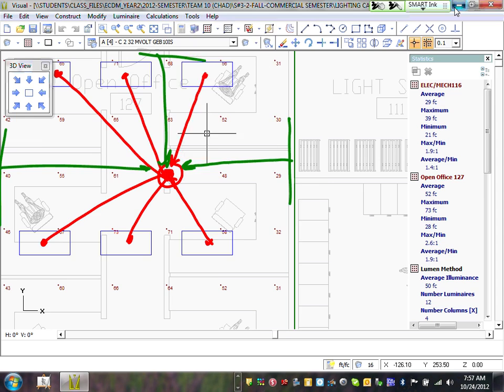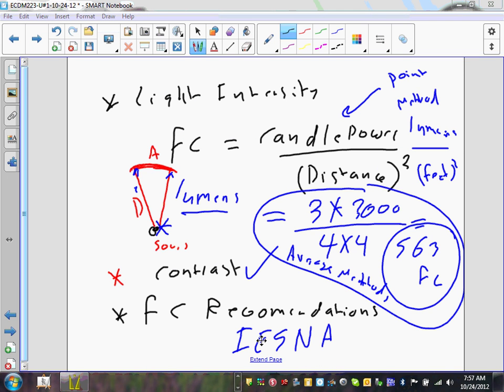Okay, so a couple of things, guys, I want to show you in a second here. There's a recommendation, IES file recommendation. Can you guys look at this page here? They have recommendations for different industries, how many average foot candles you need. Everybody can see that. So for example, examples for suggested mean horizontal foot candle value. What does mean mean? Average. What does horizontal mean? Because what's the opposite? Vertical. There's vertical and horizontal recommendation.